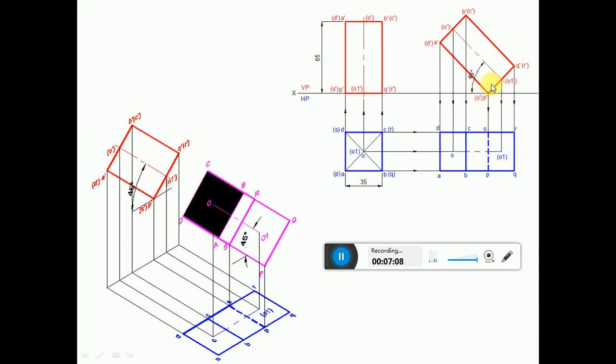So you draw that. Once you draw that, by using the compass, you measure the distance from P dash to A dash. From B dash you cut an arc on this to get this point A dash P dash. Then you mark them or you name them.